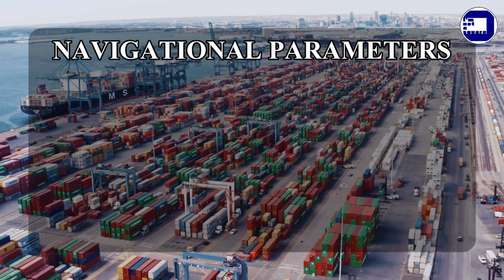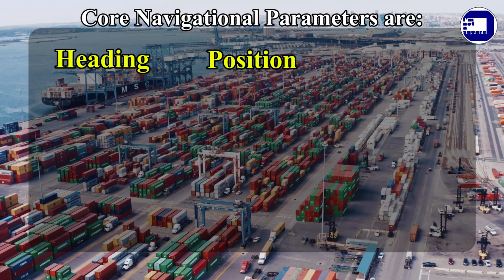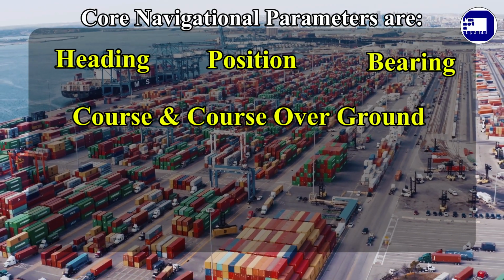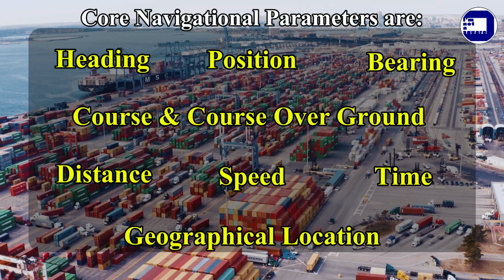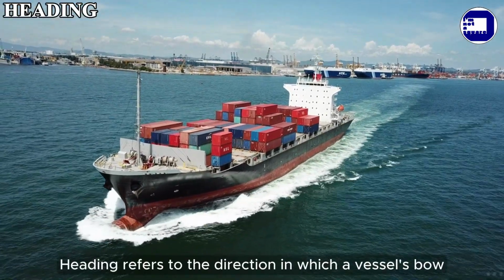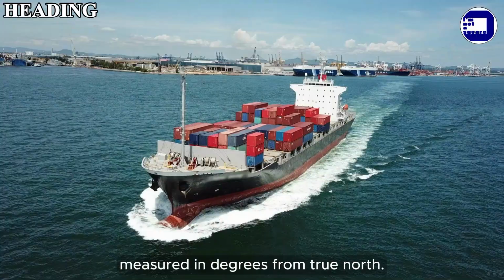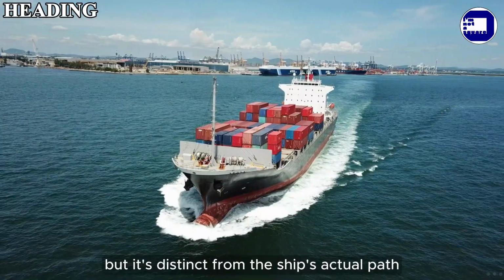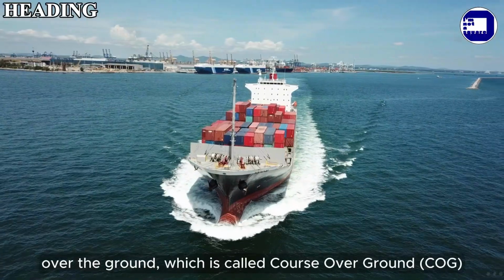Navigational parameters. Core navigational parameters are heading, position, bearing, course and course over ground, distance, speed, time, geographical location. Heading. Heading refers to the direction in which a vessel's bow, or front of ship, is pointed at any given moment, measured in degrees from true north. It is crucial for steering and navigation, but it's distinct from the ship's actual path over the ground, which is called course over ground, COG.